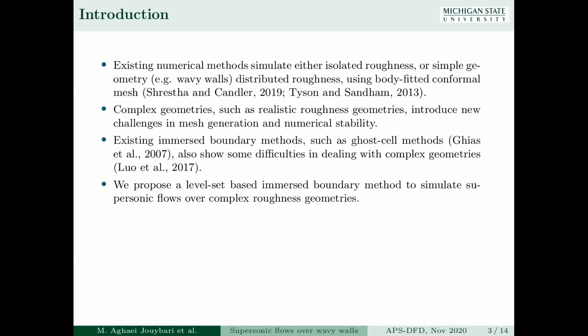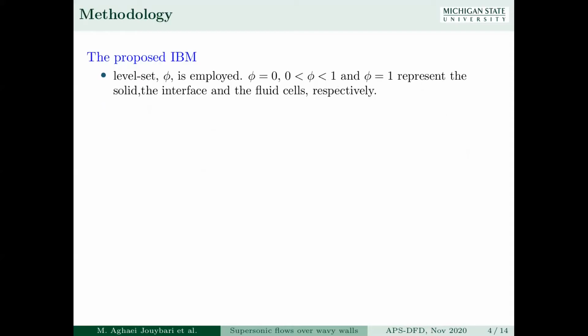We would like to propose a level set-based immersed boundary method to simulate supersonic flows over complex roughness geometries. Our proposed immersed boundary method uses a level set field phi, and it is defined such that phi equals 0 corresponds to the solid cells, phi equals 1 corresponds to the fluid cells, and phi between 0 and 1 corresponds to the interface cells.